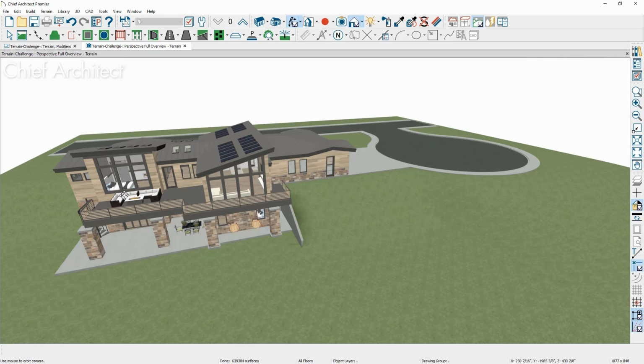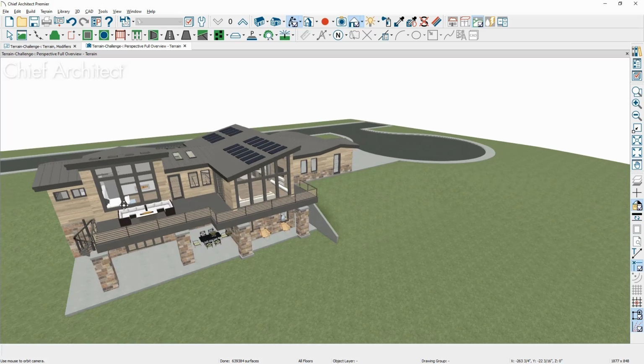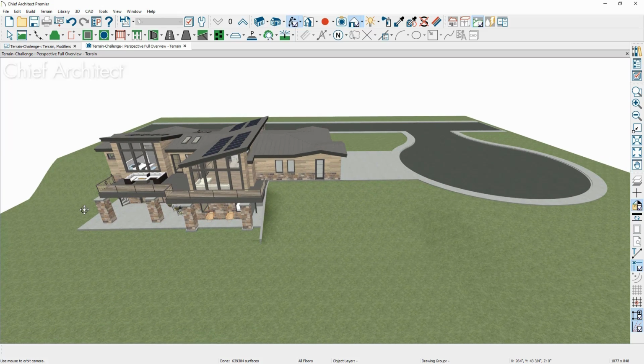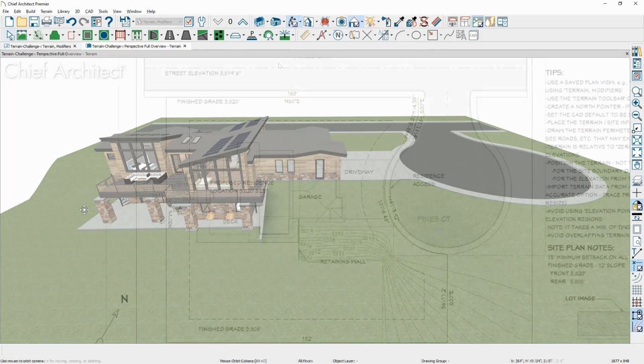And back in the 3D view, you can see that there is actually no change at all because we made the changes in all of the elevation information. If you plan to use sea level elevation information, do that at the beginning when you create your terrain perimeter, and then all subsequent elevation data will use that as the basis.